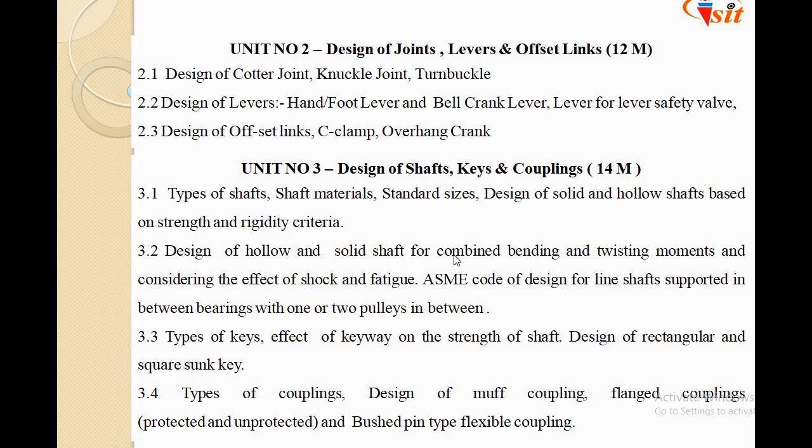Again, these hollow and solid shafts are designed when they are subjected to bending and twisting moments, considering the effect of shock and fatigue. And for that we have to use the ASME code of design. When the shafts are supported in bearings with one or two pulleys in between, as we know shafts are used for the transmission of power, transmission of torque.